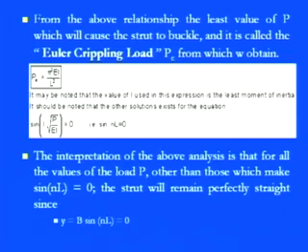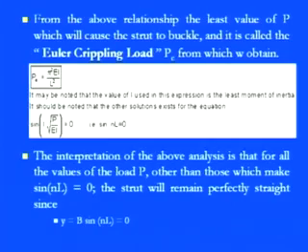Here there is a chance of deviation; if you go beyond that, there is a chance of deviation of the shape of the strut. But other than this situation, in almost all kinds of load where sin NL is not equal to 0, we can say that the strut will remain perfectly in the straight position. The condition sin NL equals 0 is the one we try to avoid.